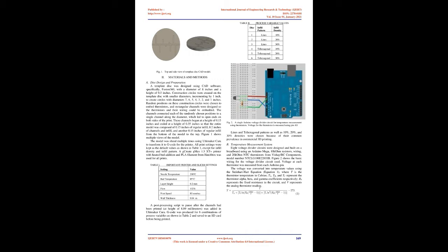However, conduction in plastics takes priority over both conduction and convection in enclosed spaces because of greater transfer of heat by conduction in plastic. Research in other fields corroborates this, as Kim and Viscontas show that increased wall heat conduction reduces the average temperature difference in a cavity, stabilizes the heat flow, and, most importantly, reduces the rate of heat transfer by natural convection. The most significant impact of their research in this context is that they find that conduction is the superior heat transfer process in an enclosure such as the internal structure of a 3D printed object.